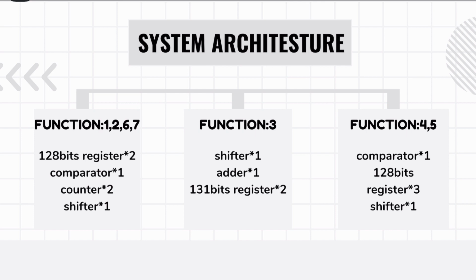Additionally, a counter is used to detect the completion of inputs. It compares two values and stores the larger number for the subsequent comparison. For functions 6 and 7, seeking the extreme value among all data, the circuit can efficiently reuse the aforementioned logic by comparing all data from start to end.